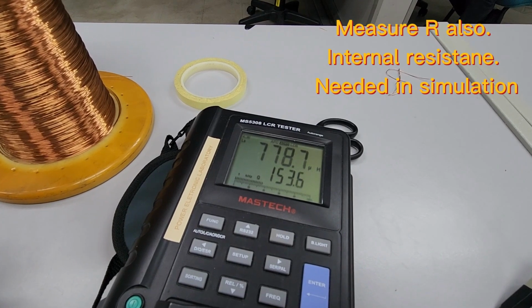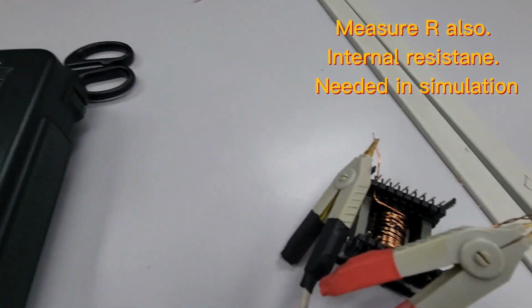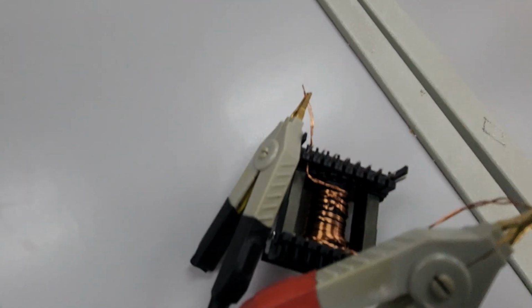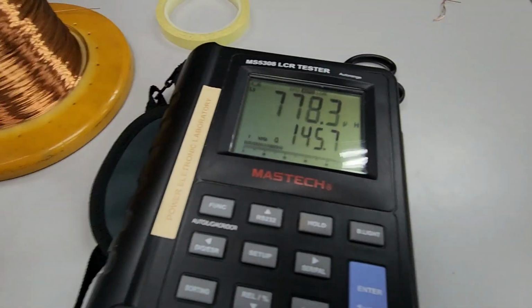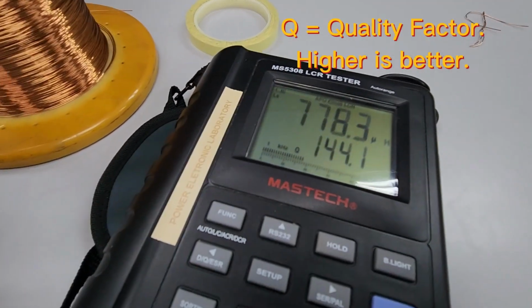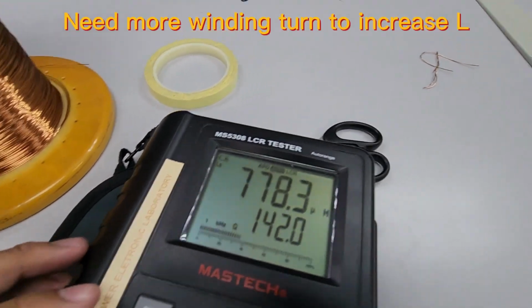778 microhenry. Before this, you can see here the winding is not very good. The winding is more or less not very good. So you can see here the quality is very bad. I think it does not achieve 1 millihenry.